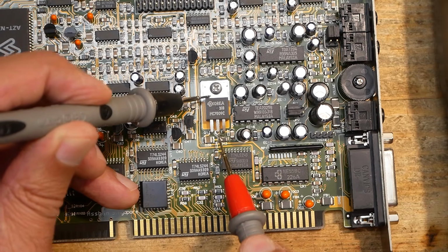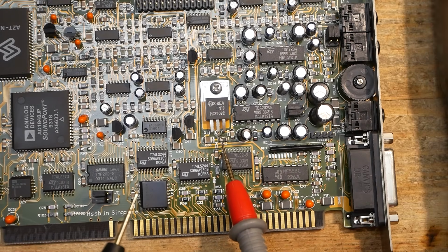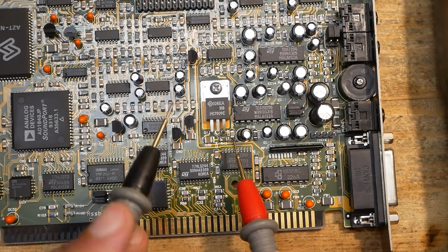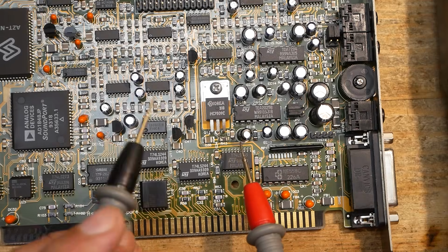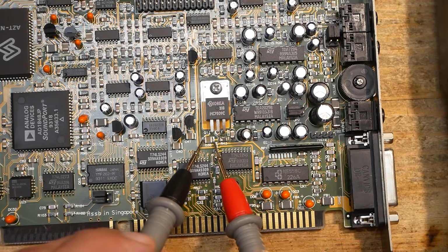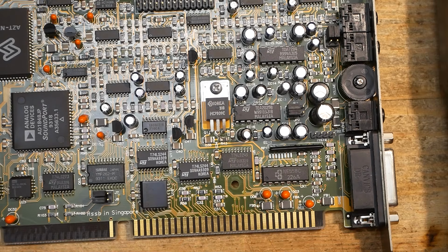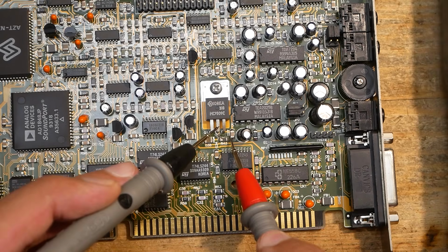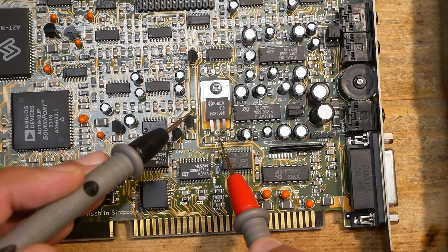Here is obviously a burn mark. The inscription on the resistor is not readable anymore, but it should be just a 0 ohm protecting bridge. The resistor is still conductive, which is bad. The point of such a resistor is to protect the circuit from overcurrent. It should burn through before other parts or the PCB get damaged. In this case, it didn't work all that well.